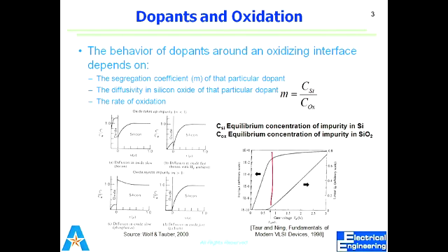We are growing the oxide, not depositing, because I told you that we can deposit as well, but right now we are discussing growing, and for that we need a silicon substrate. So this is the surface of silicon. It will also keep moving down as we grow more and more silicon dioxide.